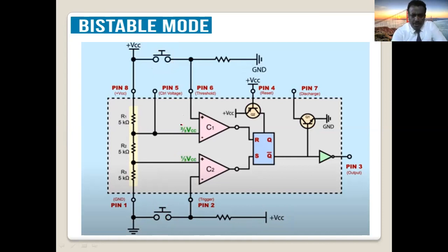This is how much volt? 8 volts from the divider. How much here? 4 volts. Okay. So let's say this switch is at off. Off means how much voltage at pin number 6? It's off, which means no connection to the battery. So we have 0 volts.